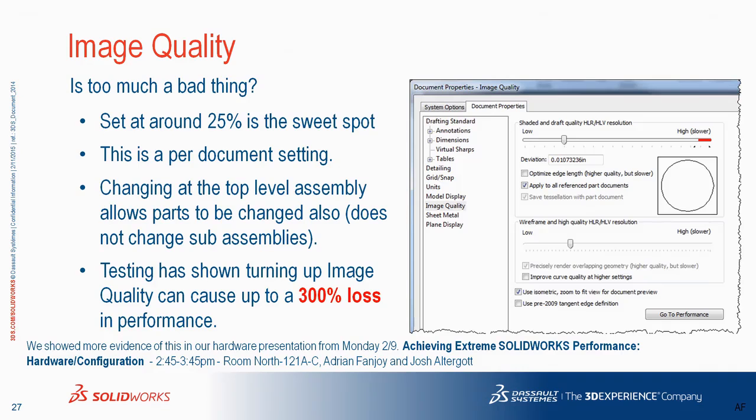Image quality. How many people have examined this setting in their system so far? All right, perfect. So you're well aware of it. Now, how many people have been using SOLIDWORKS for more than 5 or 6 years? Okay, this is very important for you guys. Check your current templates, because you guys have been using SOLIDWORKS for such a long time that you probably built your templates based on their defaults years and years ago.